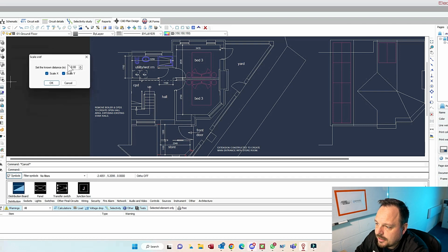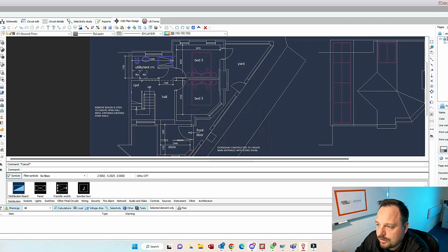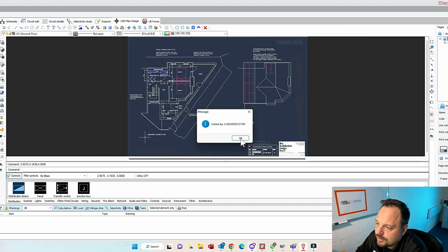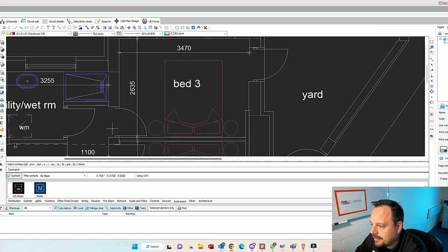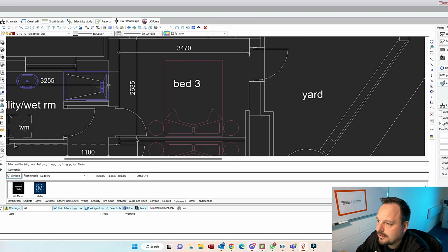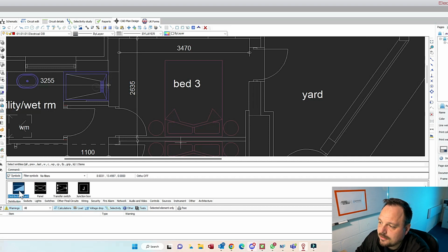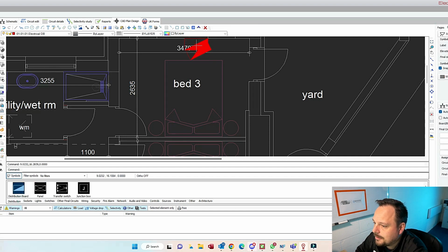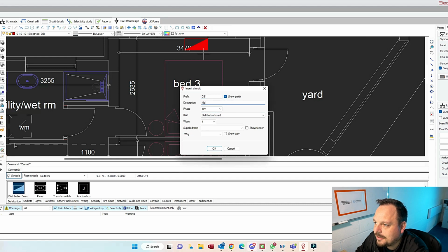We do need to set the scale on the drawing that I've imported. So this is an existing CAD drawing. There's loads of node lengths on there. You just need to pick one and then measure between the 2 points. It'll pop that in, and then anything that you do after that should bear a relation to the scale within the planned drawing. Now I should say this CAD drawing isn't exactly to scale anyway. It's not something that's been done by an architect, it's been done by the homeowner. So there are a few discrepancies in there, but it's going to give us a good idea for running through this example.